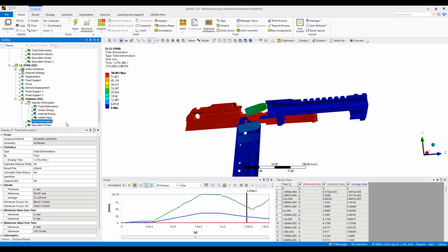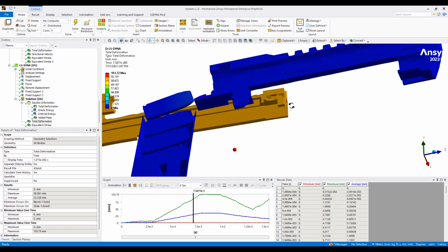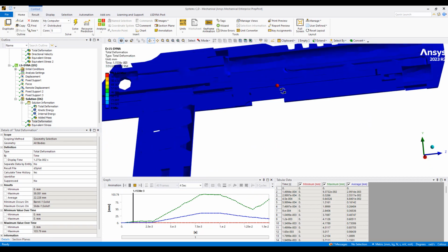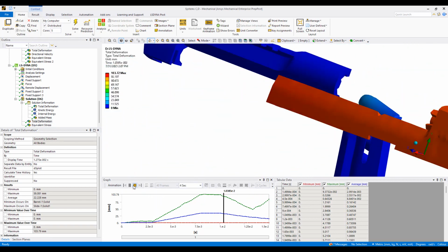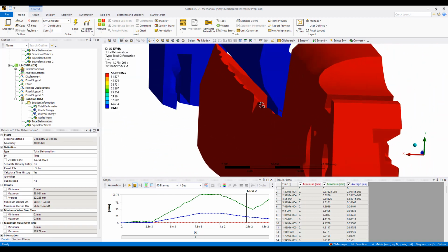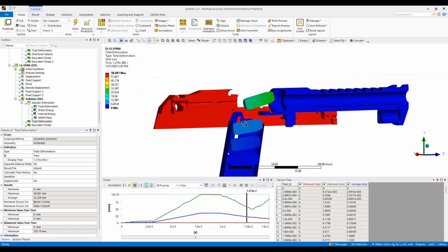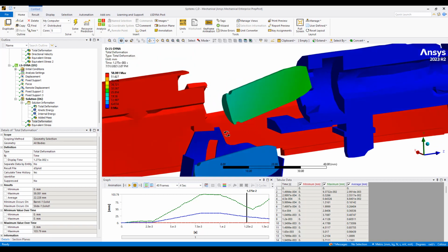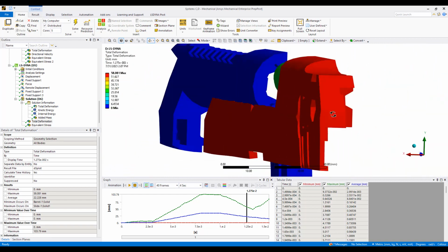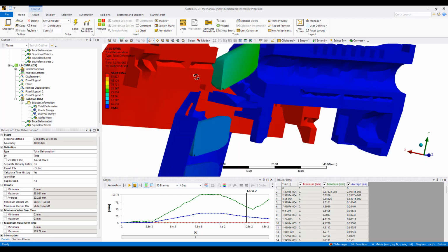So that's a quick overview of what happens when we simulate a bullet loading analysis in Ansys Ls-Dyna. You can see the vibration here. So that's not realistic, and that's probably because as I'm sliding this along, you can see the mesh is slightly bumpy, and that causes those vibrations. Lots of ways to simplify that: remove contacts from that area, smooth it out with a finer mesh, or set up displacement constraints so you don't have these jagged edges rubbing against the other parts.